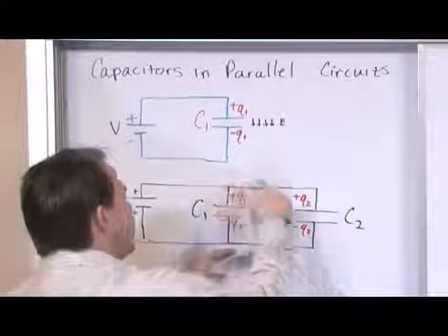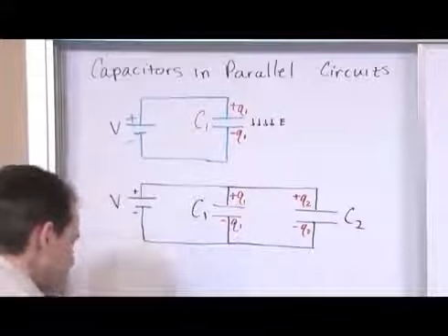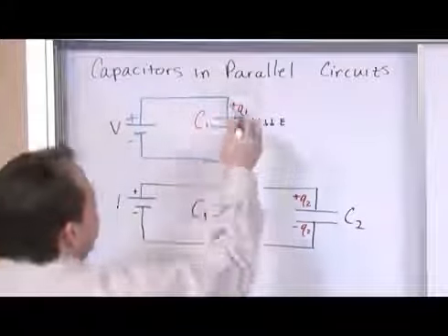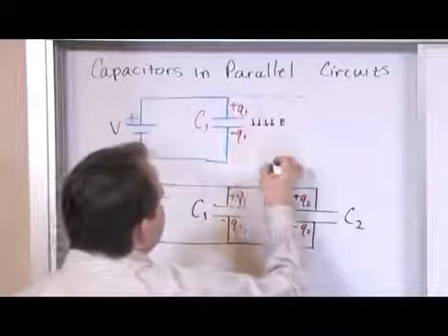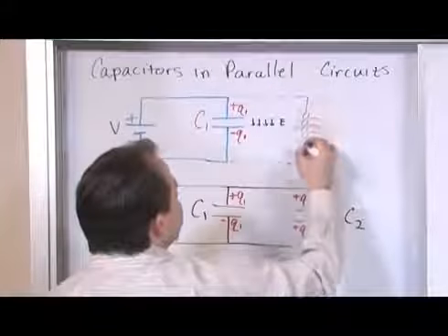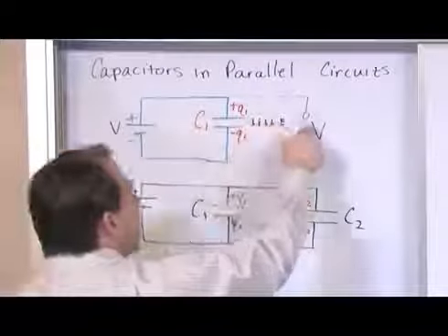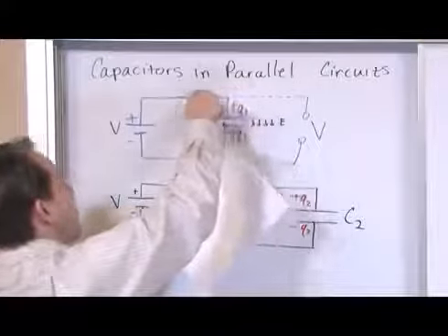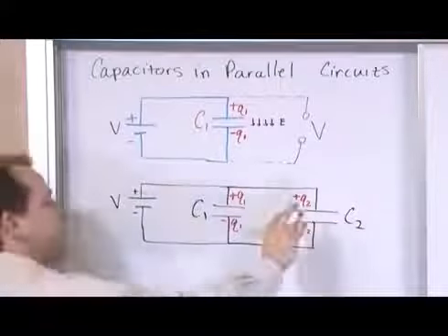And this capacitor here, yeah, this guy's in the circuit too, but he is also directly connected to the voltage source. If you were to put a voltmeter, a little meter that you can buy at Radio Shack or someplace else, across there, then you would read the voltage V. So if this were 9 volts, you would read 9 volts. Even though the capacitor's here, you're connecting your meter directly to the battery terminal, so that's what you're going to measure.